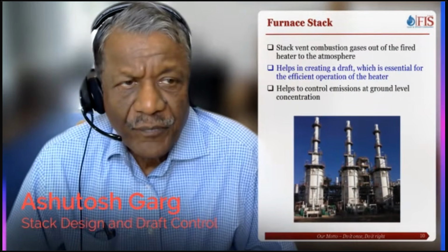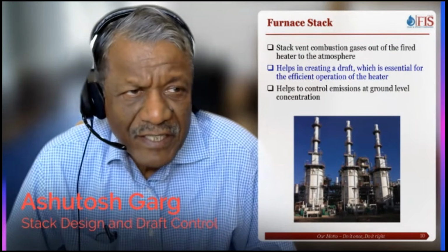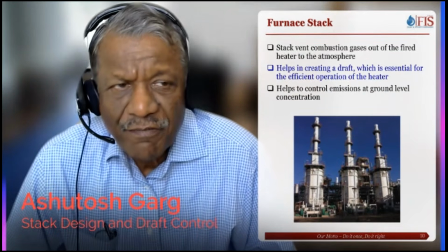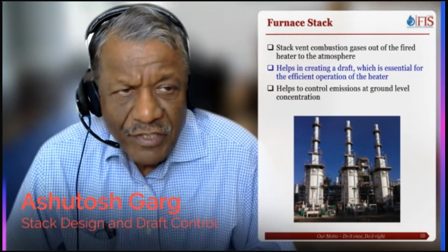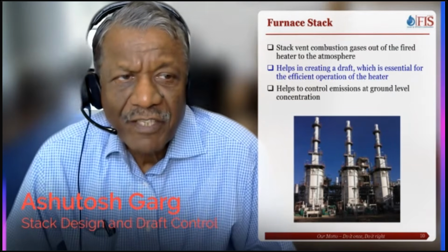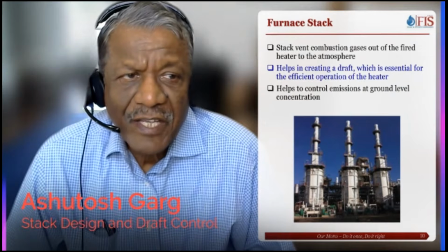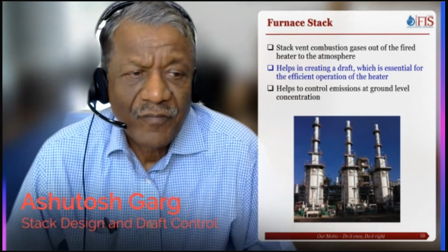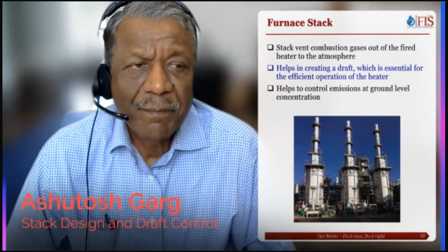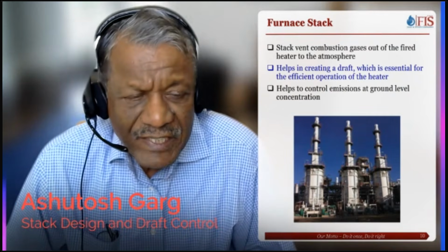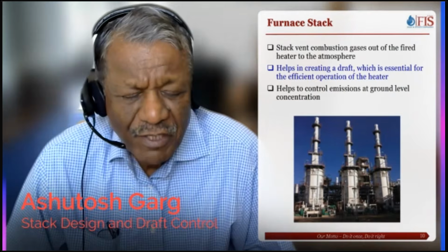So, three functions of the stack, as I said in the beginning: safe disposal of flue gases and controlling emissions. The most important function of the stack is to create a negative pressure inside the fired heater. Fired heaters are very different compared to boilers. Most of the technology in fired heaters came from boilers, because boilers have been around for I think 400 years now.